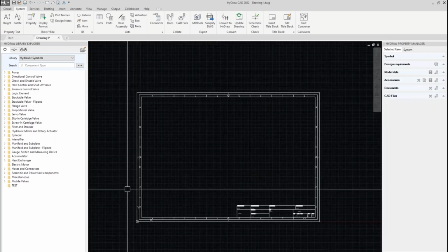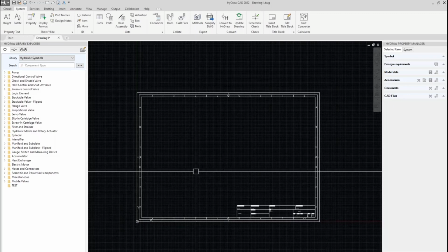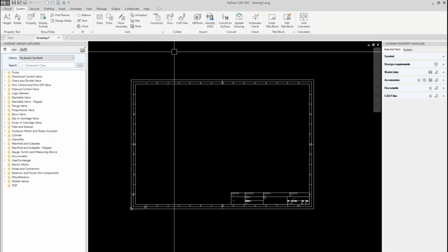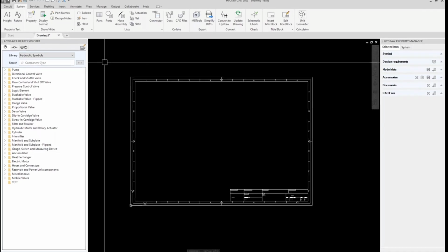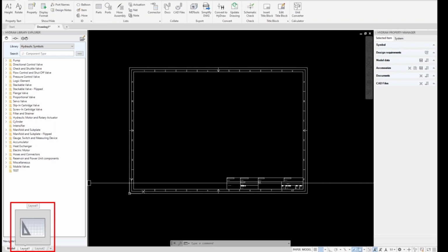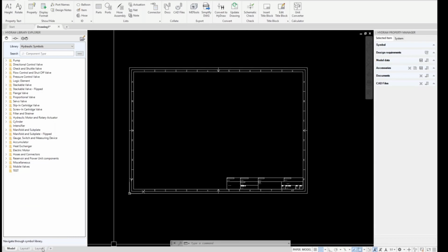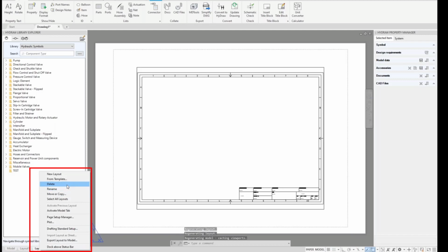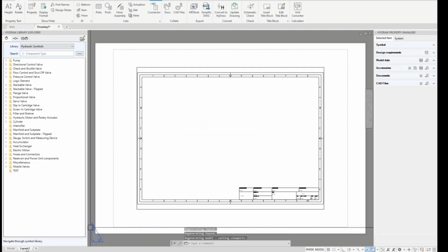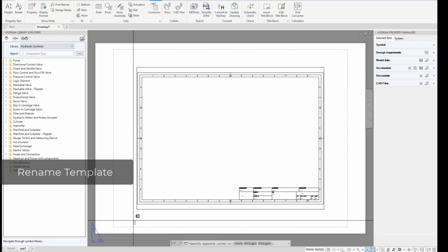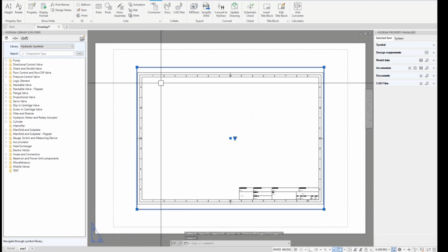So now, although many of those that are familiar with the AutoCAD interface will directly plot from model space, I really prefer working in paper space. So paper space is down here, layout 1 and layout 2. So let me quickly show you how to configure my layout in order to print properly. So I can just delete a layout that I don't need. This one for me is page 1. So I can rename the layout,